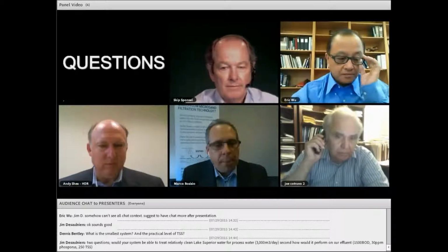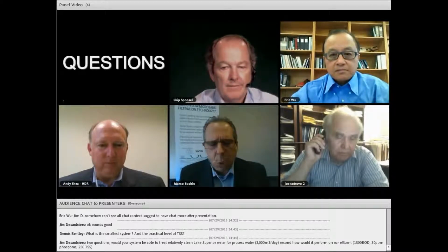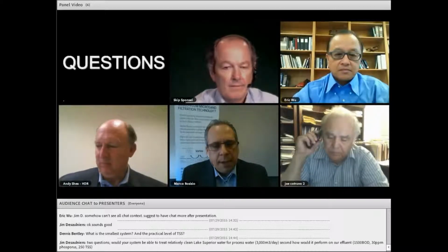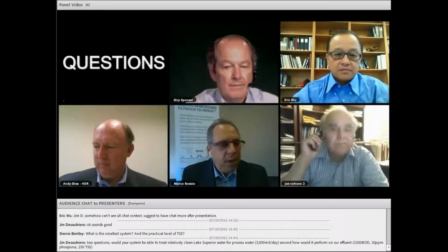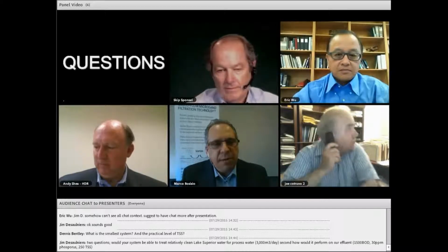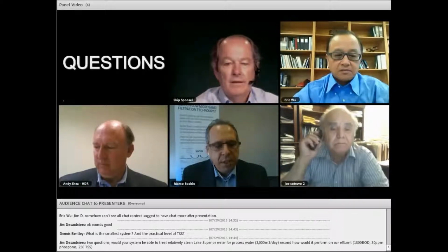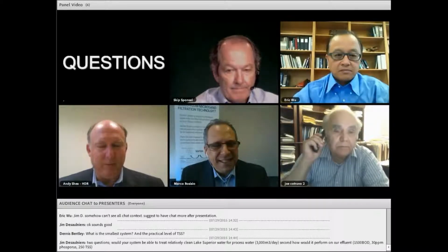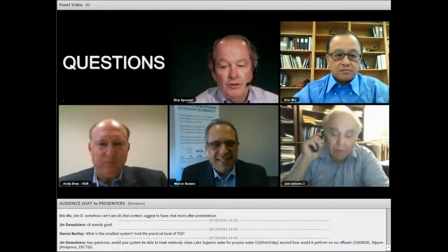So we do have to top up some of the sand once per year, probably once every 6 months, making sure that there is always microsand on top. But designers know that we need to always add some sand from time to time to media filters. So it's pretty much the same thing as other filters. Did I answer your question? Yeah, no, that's great. Appreciate that. Joe, do you have one?